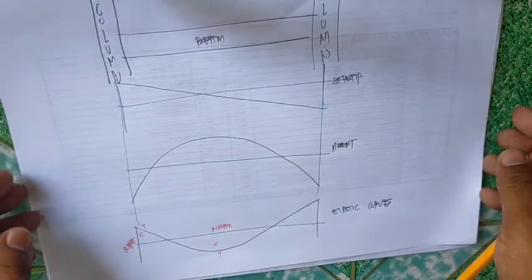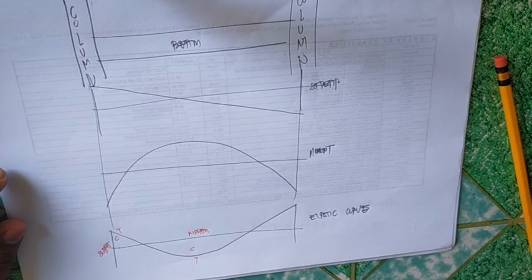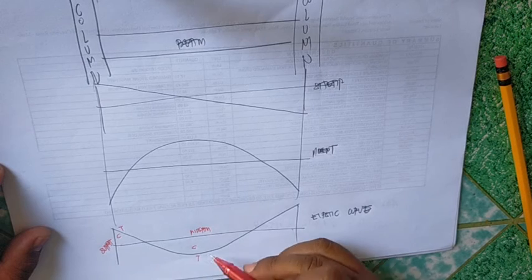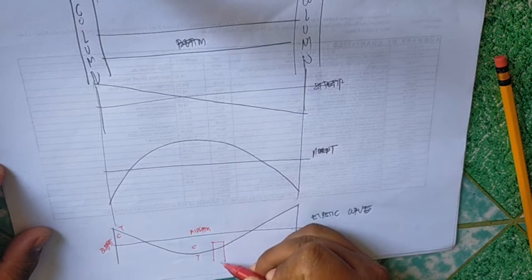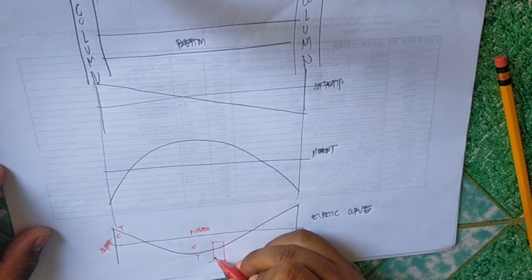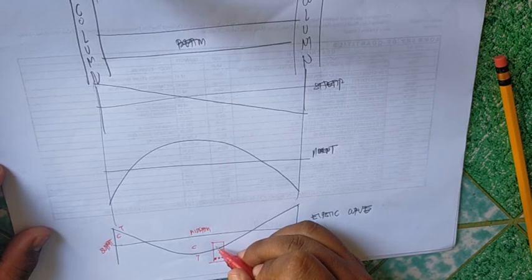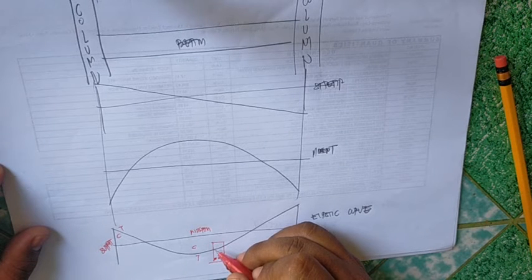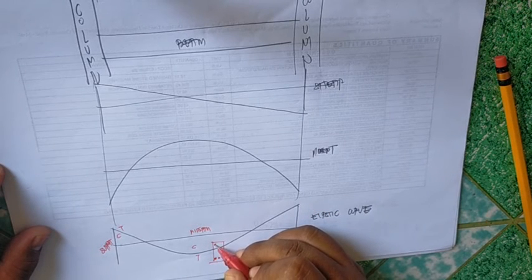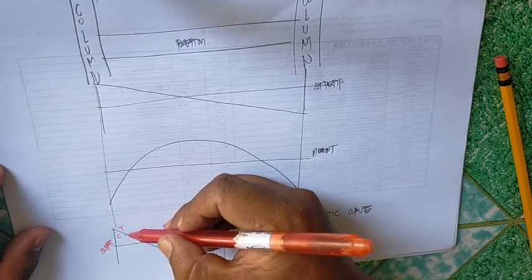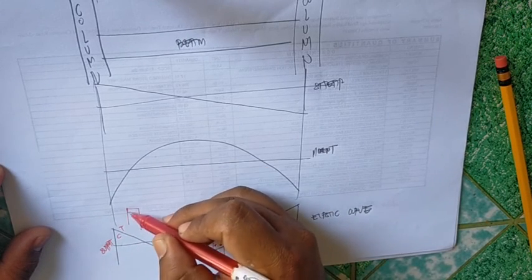So if we look at the concept that we discussed, for the midspan, if this is the cross section, you need to provide more reinforcement at the bottom, and here it can be less, depending on the size. But when we talk about singly reinforced only, we can have, let's say, 2 for the purpose of your stirrups. Here it may be the reverse.